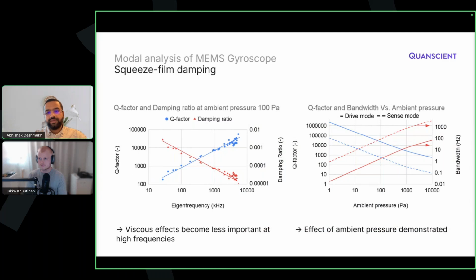Actually, that was the first simulation which I did before we took into account these environmental effects, because they need special treatment for the rarefied environments, where, when the viscosity enters the molecular regime, we cannot model this as a continuum approximation. If we want to use this approach, we have to modify the viscosities with some specific models, and this is what we did. But we started first with ambient pressures and then went on adding more effects.